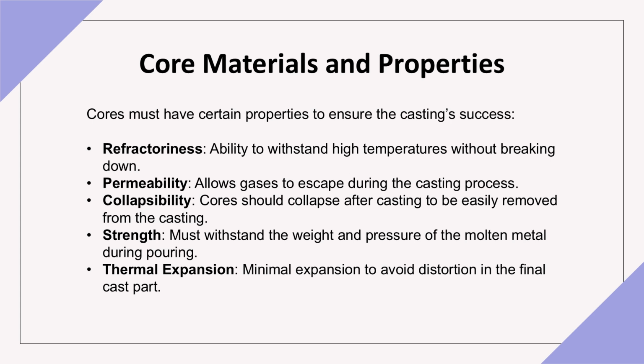Collapsibility, after casting, cores should easily collapse or break away for easy removal. Strength, cores need to withstand the weight and pressure of molten metal during the pour. Thermal expansion, minimal expansion is necessary to avoid distortions in the final cast part.